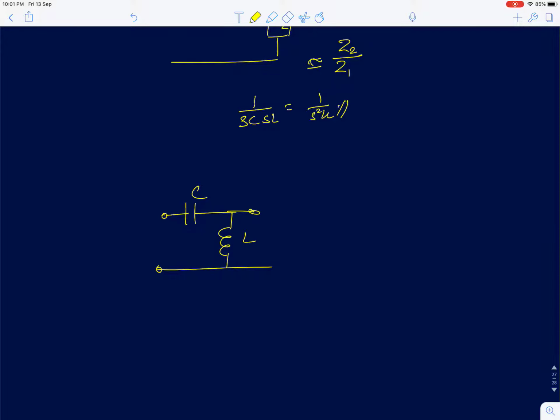So in this circuit, to find the transfer function, you can see the H of infinity at very high frequencies, or you can find the DC gain. At DC, the capacitor behaves like an open circuit, and the output at this node will be 0 because the impedance of the inductance will be very small, the impedance of the capacitance will be very high. So you have a condition where both the impedances act in such a way that both will give 0 at the same point.